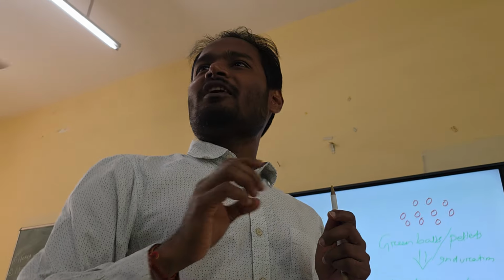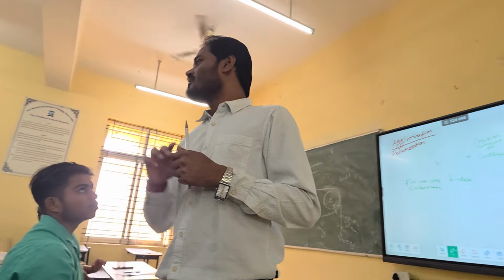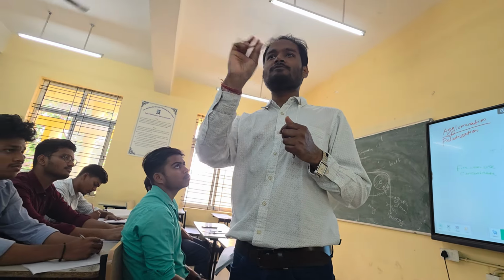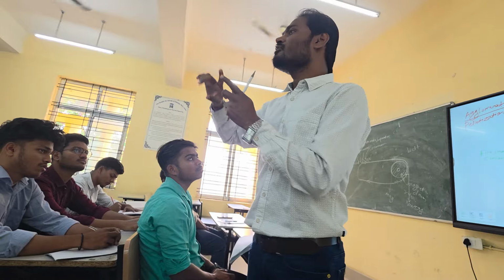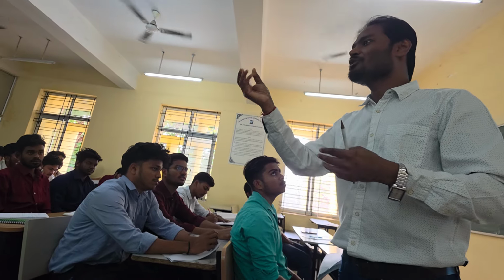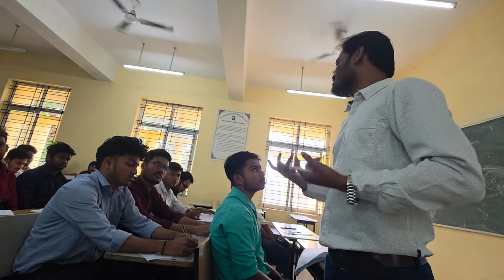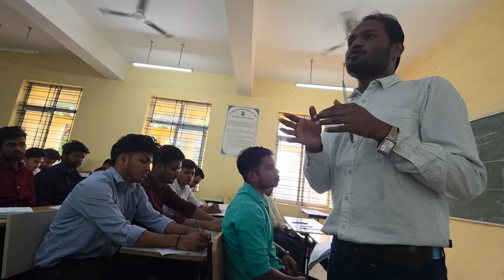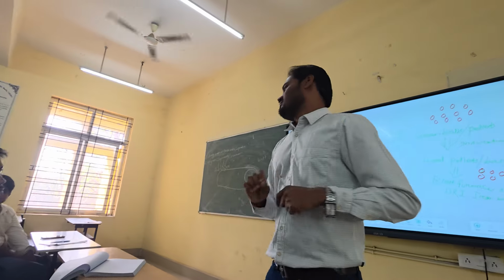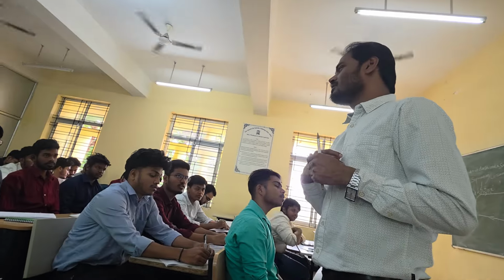And another advantage in terms of shape: just see the shape of the pellets, they are spherical, nearly spherical, or egg shaped. But in case of sinter, that was a big lump, you crush it, but during crushing you will not get spherical balls or spherical shaped sinters. It may be an uneven surface, right? So now you tell me, which one is good actually, technically? Spherical balls is actually good.